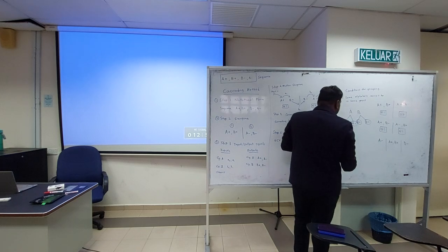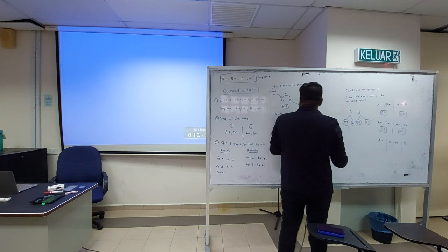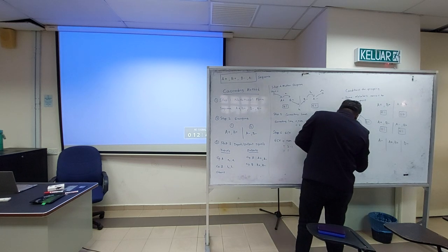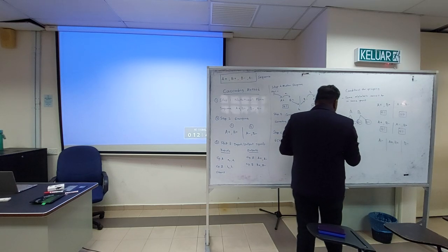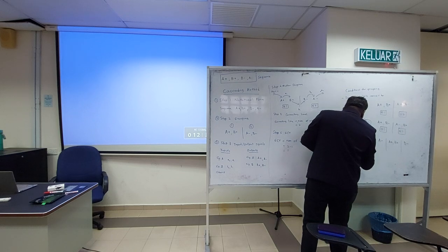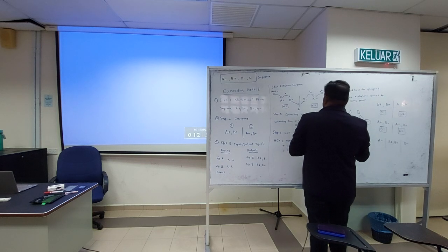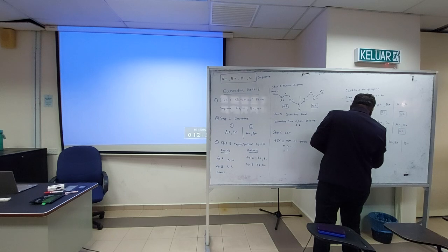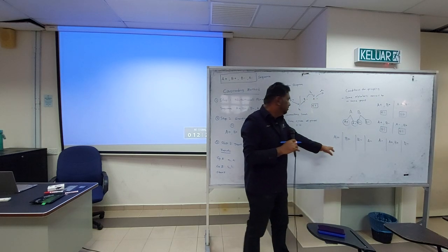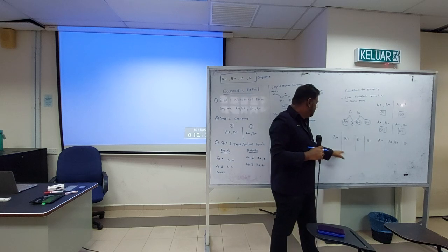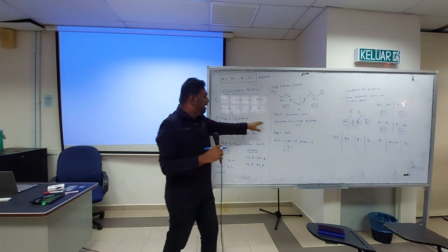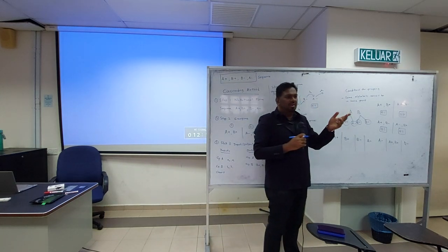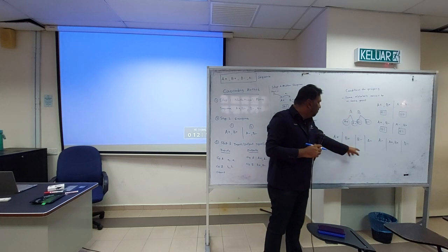A plus, change group first, B plus, then change group back, B minus, and change group back. So you have to change group 3 times if you use this sequence, because you have to follow the sequence to activate. There will be switching because of the group changing valve, which will change 3 times.